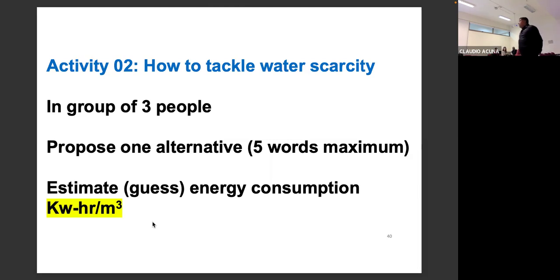Today it is discharged directly to the sea, and depending on the current, in general, it's diluted and dispersed, but it depends on the country. In the Middle East, you need to discharge it very far away, kilometers. Here it is 200 meters. But since the plant has worked for 30 years, you will end up with metals. You will end up with cadmium and lead, and that's the problem. So what we should be doing is taking care of this solution, evaporating it and converting it.